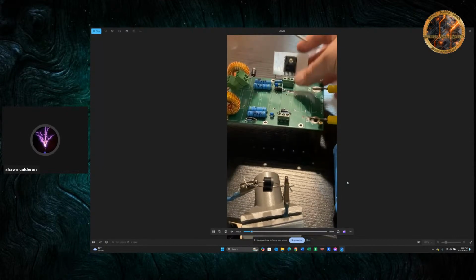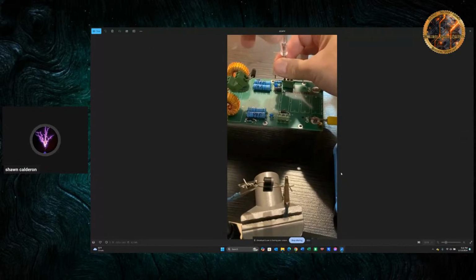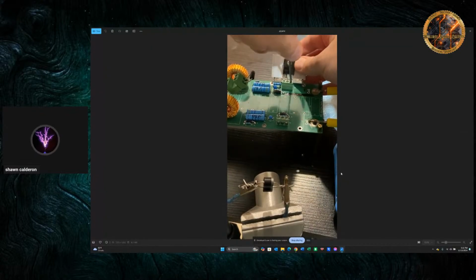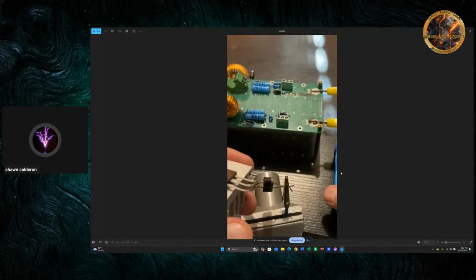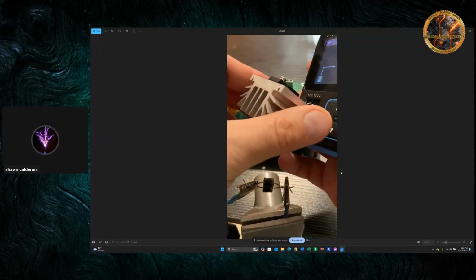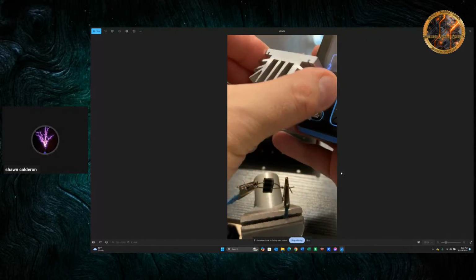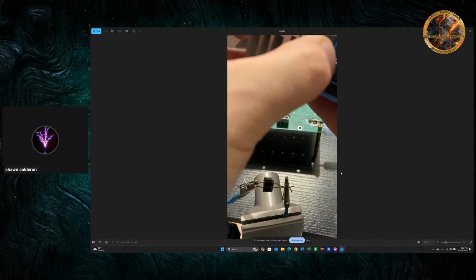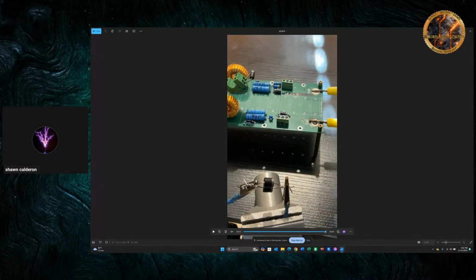All right, so the third culprit now are the MOSFETs. So I use these terminals because I can take out the MOSFET. Awesome. I can get my little transistor tester. It's this little blue oscope that I picked off on Amazon for like 40 bucks. Here I am trying to fit it in there, and I couldn't quite get it in there in this video.